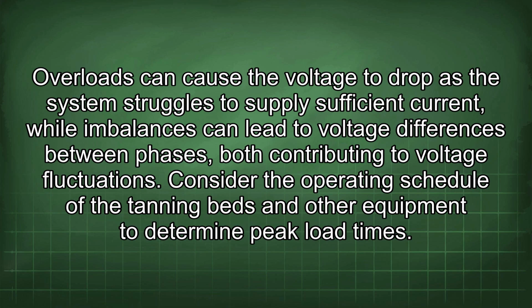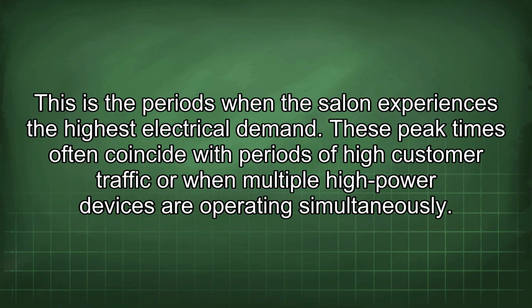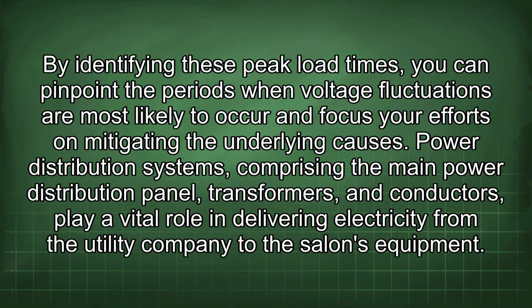Consider the operating schedule of the tanning beds and other equipment to determine peak load times. This is the period when the salon experiences the highest electrical demand. These peak times often coincide with periods of high customer traffic or when multiple high-power devices are operating simultaneously. By identifying these peak load times, you can pinpoint the periods when voltage fluctuations are most likely to occur and focus your efforts on mitigating the underlying causes.